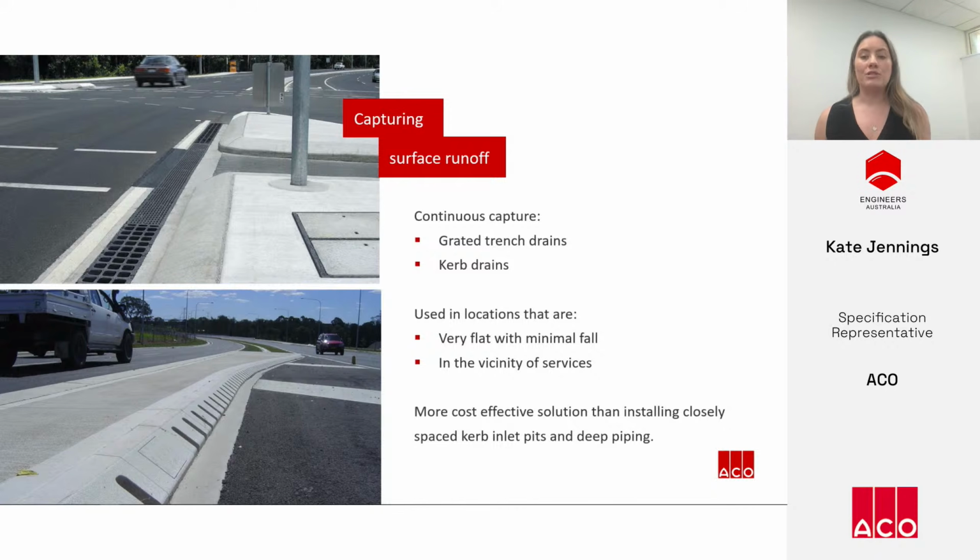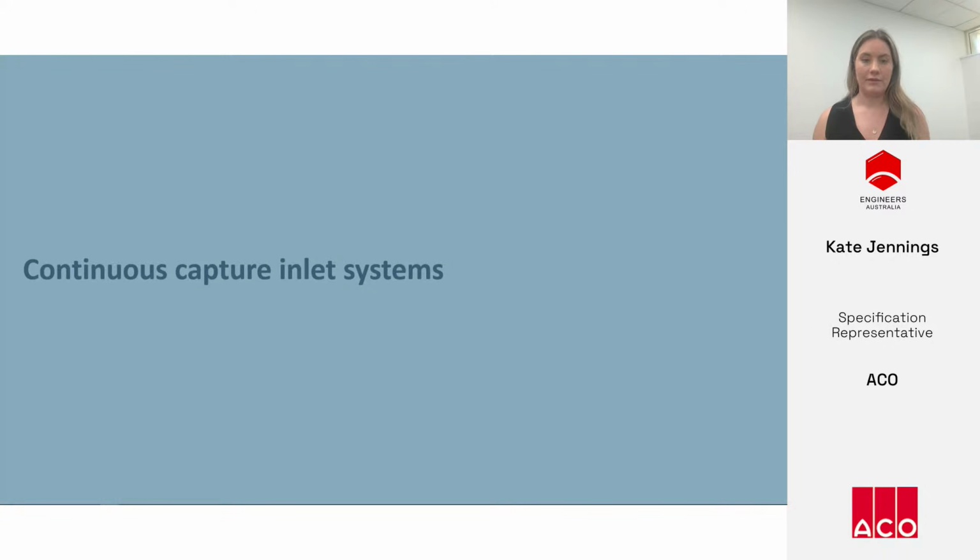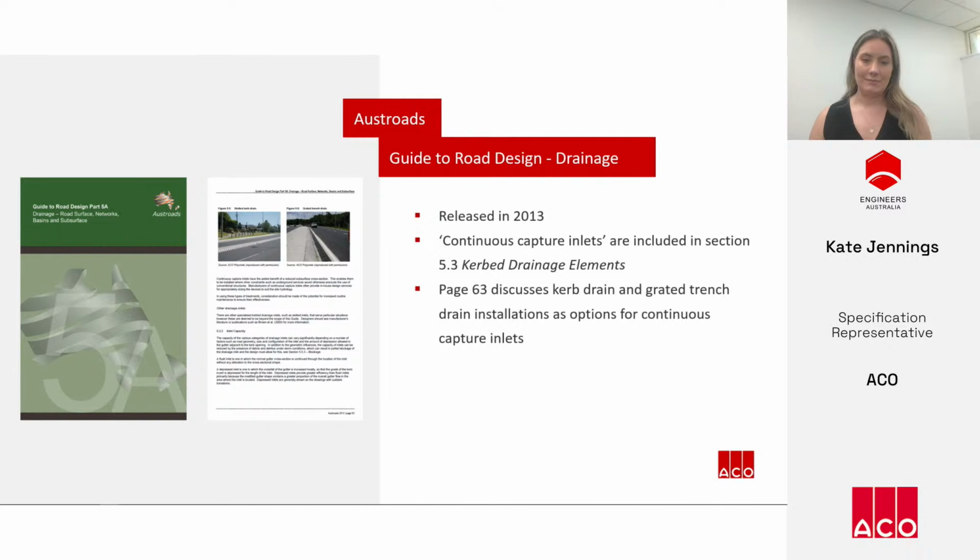These are very much problem-solving solutions and would be used in areas that are very flat with minimal fall or have services in the ground close to the surface. These continuous capture systems are more cost-effective solutions than installing closely spaced traditional curb inlet pits and deep pipe work, and we'll look at that in more detail later on in the presentation. Let's focus now on continuous capture inlet systems.